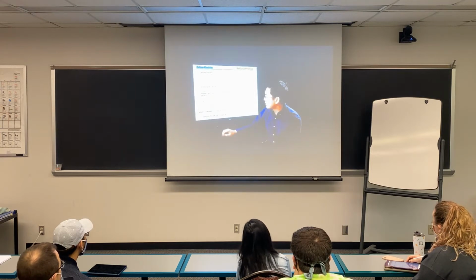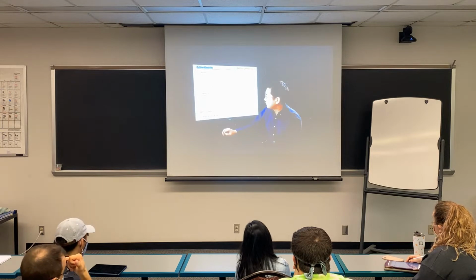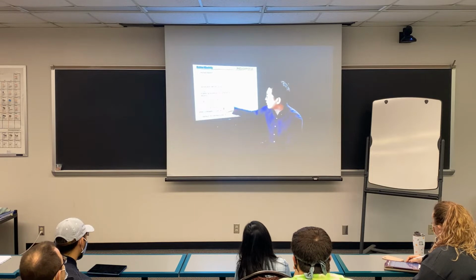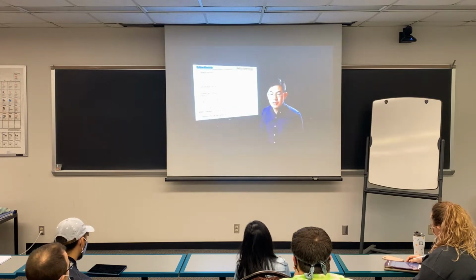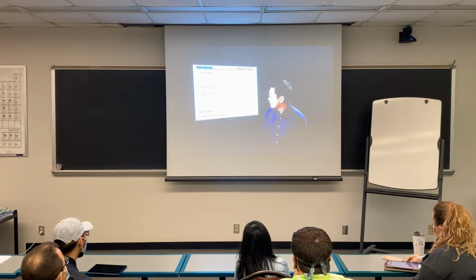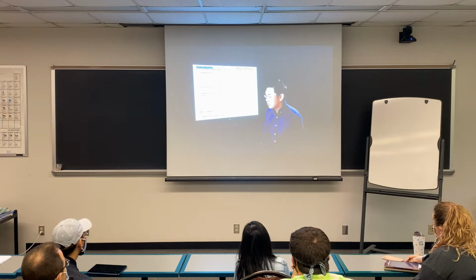VX is a consideration of after we crosslink, or after we modify this phantom network, what is the phantom network's influence or correction factor? So VE minus VX will be the real crosslink density, while VE was originally the crosslink density without accounting for the phantom network.